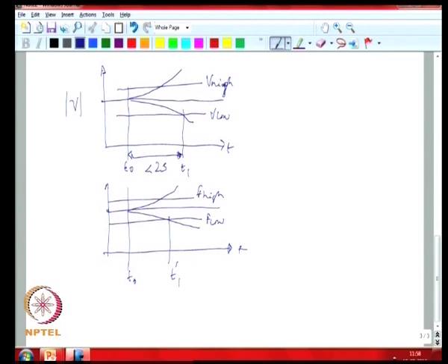The disconnection can happen anywhere upstream on the feeder, and the DG can be located anywhere along the feeder. After the disconnection, the unit which is making the detection of whether it is an islanded situation or not is detecting its voltage locally. It is not able to detect at some other point. So it is taking that measurement on a local basis, and based on the local measurement it is making a decision whether to stay connected or to disconnect.